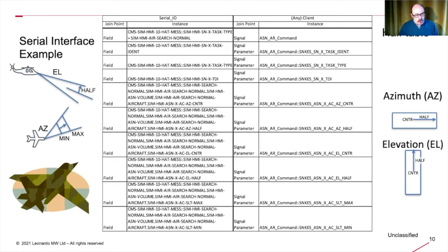And so what we can do here is the code generator, in this case, will actually generate some C++, for example, which will hook itself up to an interrupt, and that interrupt will go off when a message arrives on the 1553 bus, and it will generate C++ code to mask and shift the data out of the arriving buffer and convert it and place it into the appropriate signal parameter.